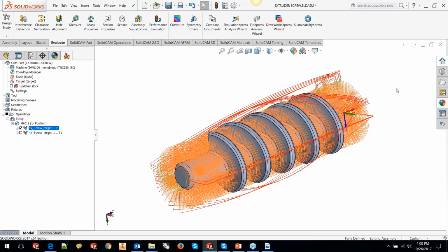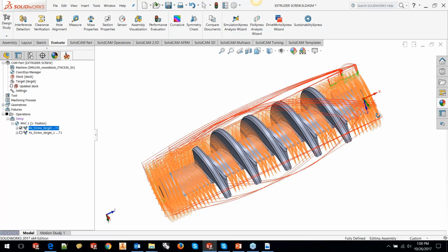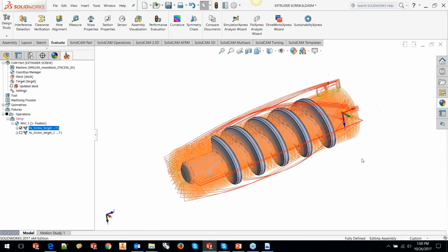Okay? So 15 minutes to calculate roughing. It's like simple 3-axis. There's nothing complicated in the definition. You just say, I want to machine from here to here. This is my model. This is my tool. This is my depth of cut, my side step. Calculate. Calculation is done.